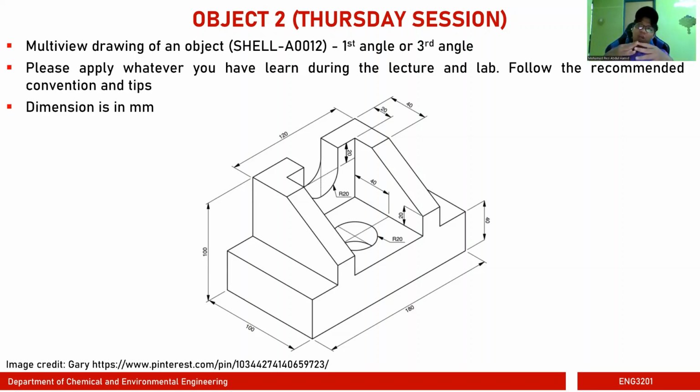In the third angle view, you have the empty space on the first quadrant, basically your top. For the third angle view, you will have an empty space on the top right corner of your drawing layout. But if you use a first angle view, you will have an empty space on the bottom left corner of your drawing layout. And then you have a top view, front view, and then side view. Again, depending on the situation, you can remove some of the views because sometimes they are redundant and do not add new information.